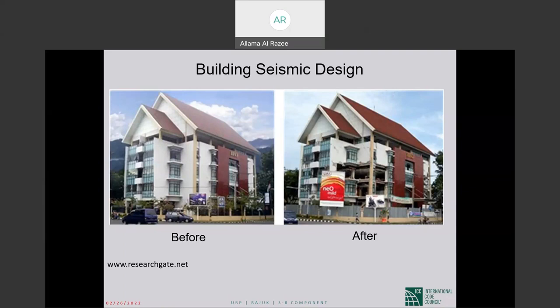We can design for earthquakes with a return period of 2,000 years, 5,000 years, because they are much larger earthquakes. But even for that 475-year return period, that is the base of our design code.